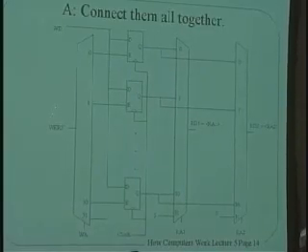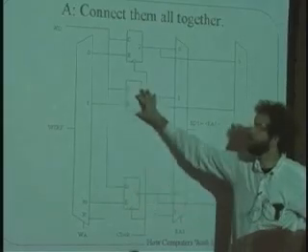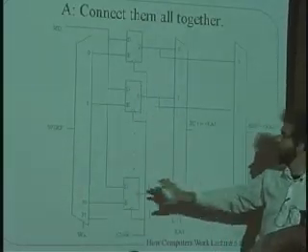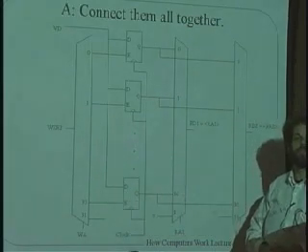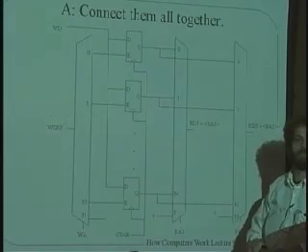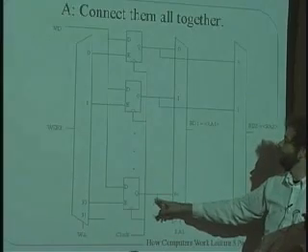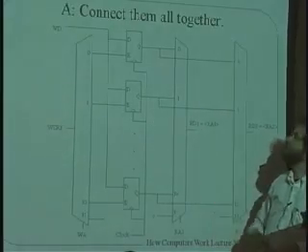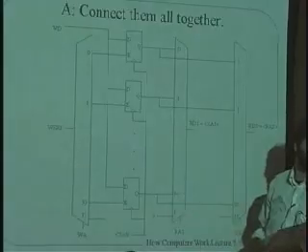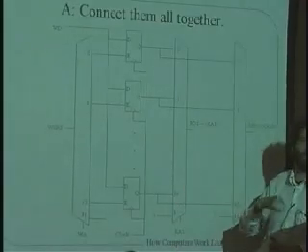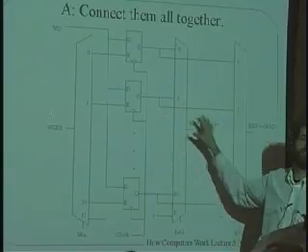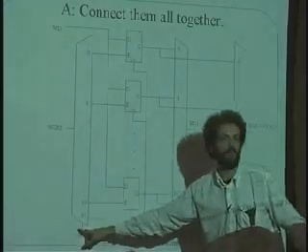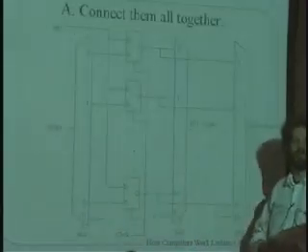It's really simple, okay? And each of these units is exactly the same kind of device we talked about in the last few classes, and the same sort of device that's going to be used to hold the contents of the PC, for instance. A simple 32-bit register. 32 wires come out of each one of those. That's absolutely right, yeah. If I wanted to, I could mess this thing up by putting a slash on each one of the wires here and putting 32 on each one of them. But the truth is that this works no matter how many wires come out of each one. So the architecture is general. In our specific case, yes, you are right. All of the data paths are 32 bits wide. The address path is 5 bits wide, and everything else is 1 bit wide. Yes.